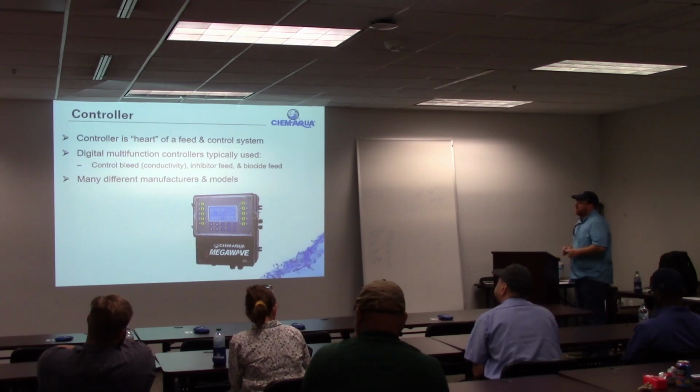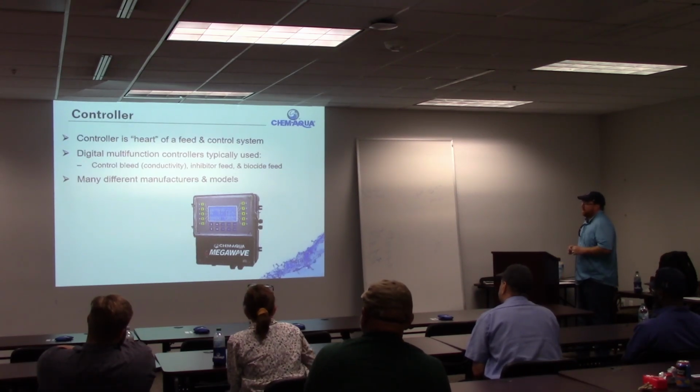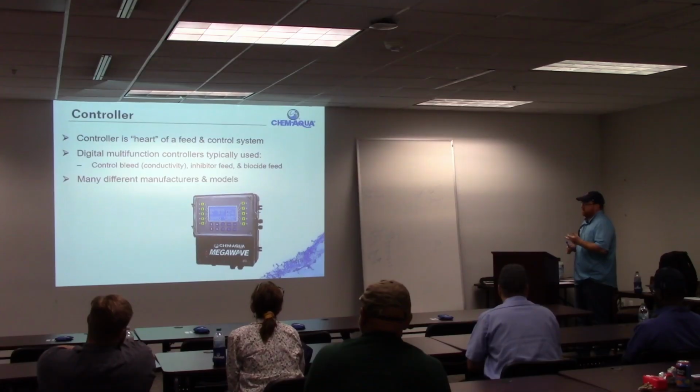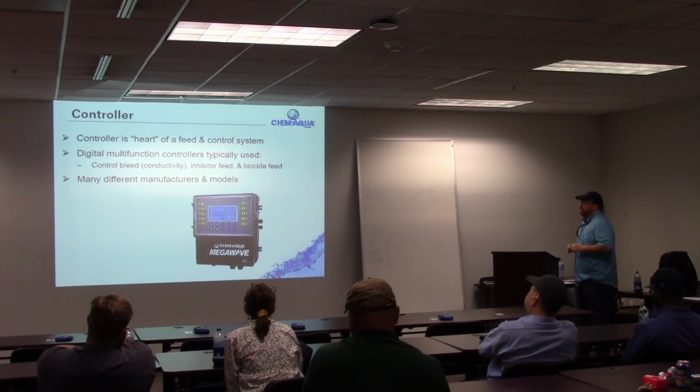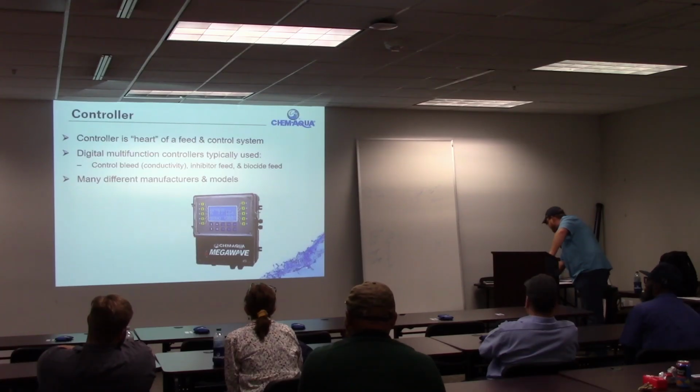So this is a controller. I'm sure a lot of y'all have seen something that looks like that, but that's what's going to control your blowdown by monitoring conductivity. You're going to control your inhibitor feed with that. You're going to control your biocide feed with that. That's kind of the heart and soul of the chemical feed station.